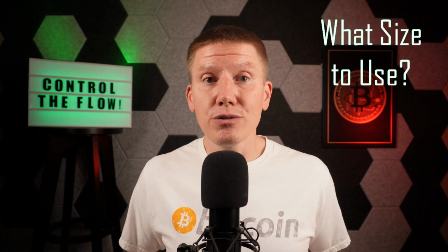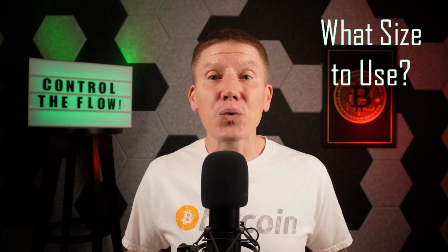Now, with a brazed plate heat exchanger, the most important question you have to ask is, what size do you use? And this is actually a really tough question to answer. You have to know the fluid flow rates in both coolant loops, the temperature changes in one of the loops, thermal properties of both fluids, heat transfer properties of the heat exchanger itself. It actually is a pretty complicated problem to solve.